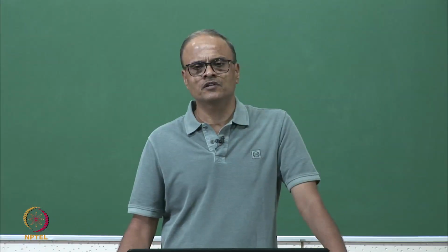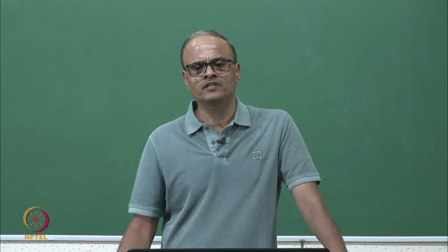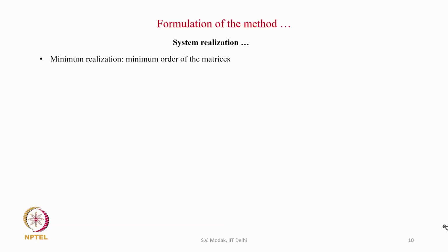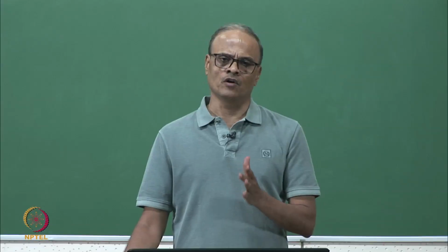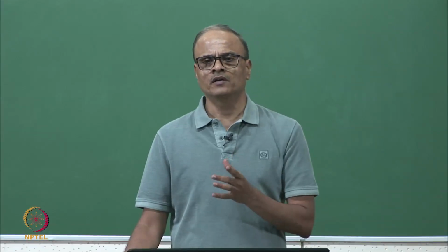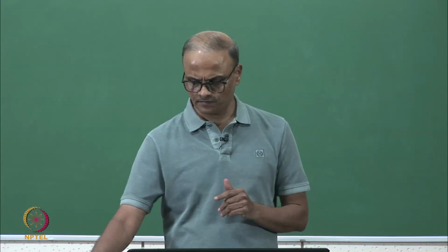The minimum realization corresponds to the state space matrices which are of minimum order. Now, the eigensystem realization algorithm makes use of the singular value decomposition in order to determine the minimum order of the matrices.